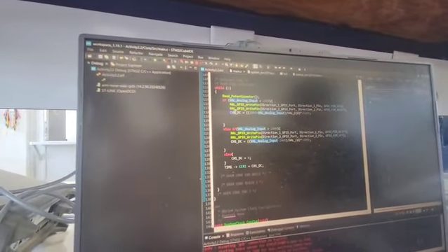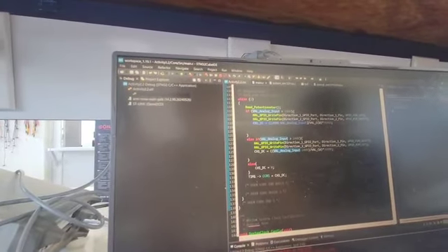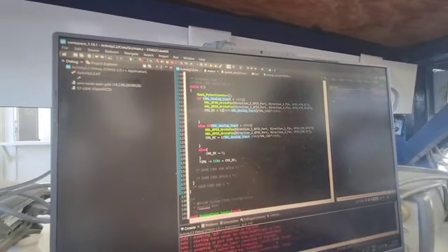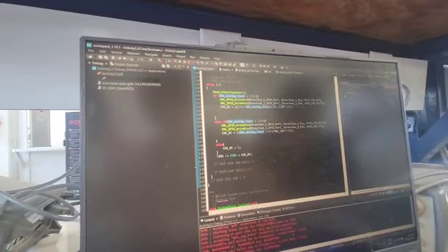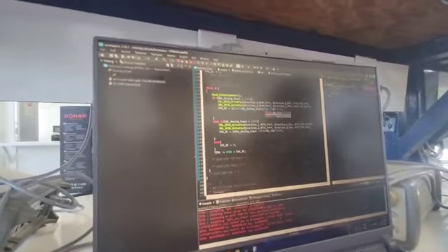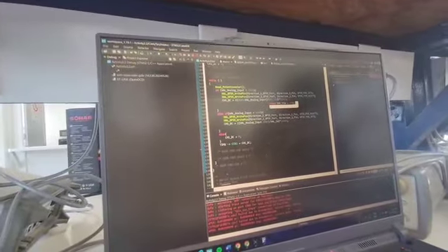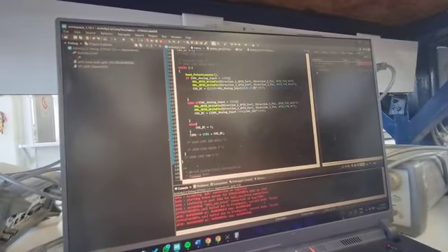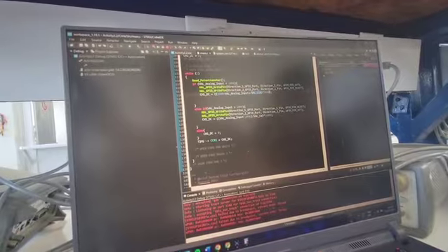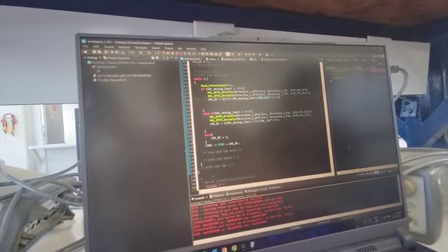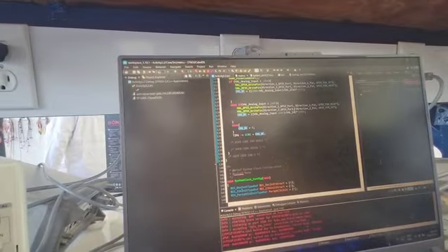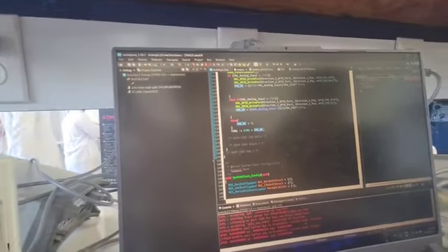0% duty cycle. To convert the duty cycle in the counterclockwise configuration, we subtract from 2000 the value of analog input, and then this variable, that it's a float with a value of 1999, it's divided in to get a percentage to get the duty cycle, and then we multiply by the 36,000. So in CH1 we get the CCR value, and similar here we get the analog value.